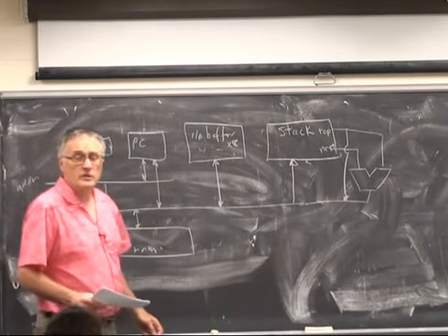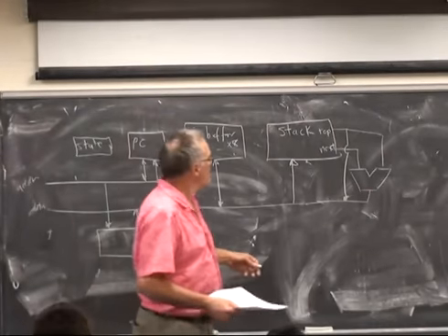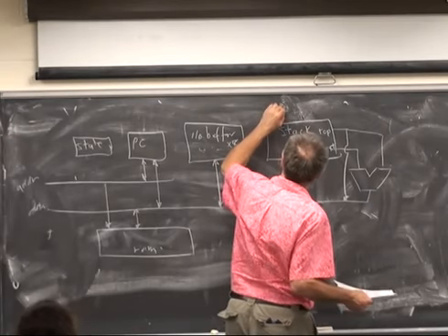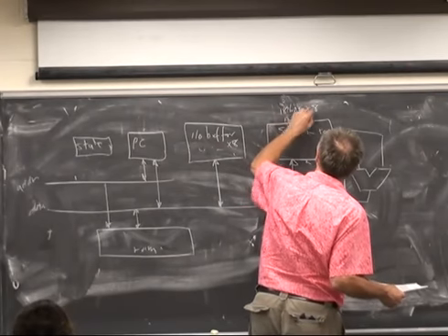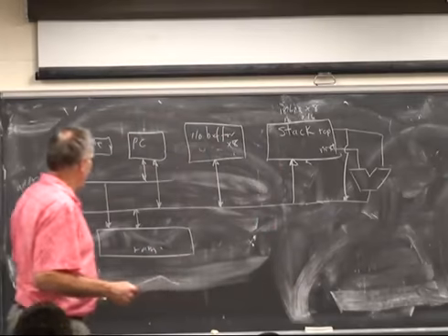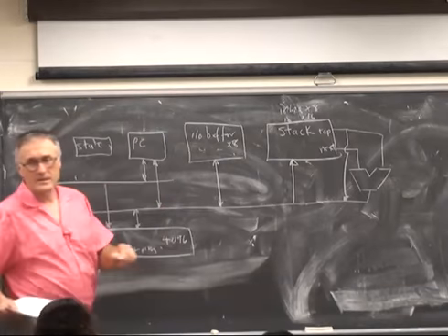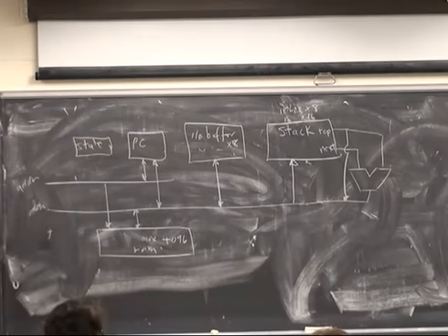The stack you can choose the size of. Can be any size you want, but the two sizes I was using is either 18 bits by 8 words or 18 by 16 words. RAM is for a maximum of 4096 words, max. You get to choose the size of memory depending on the size of the program and the data you need, but it can't be bigger than 4096 words.